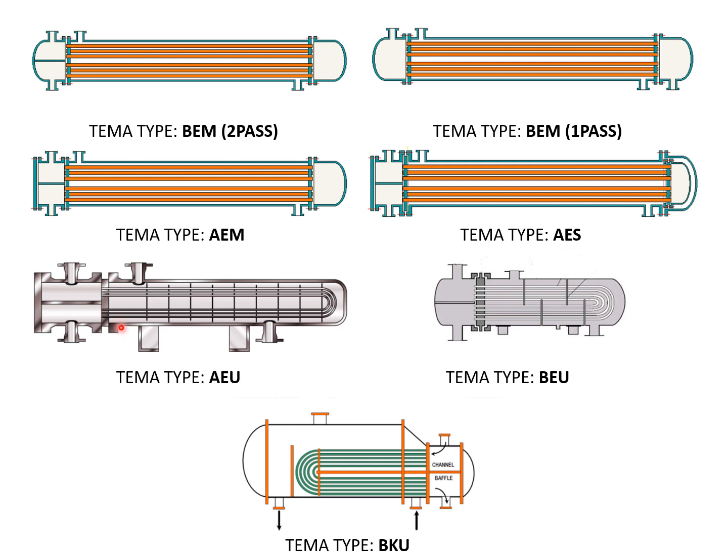So AEU. AEU means you have A, same as this exchanger. You have a removable type of bonnet over here. Then you have the same E, one pass shell, but here you have U-tube. U-tube means the end of the exchanger will not have a bonnet over here, but the liquid which is going through the tubes will have a bend in the tube itself. U-tubes are ready-made tubes available in the market, and the liquid will come over here and come out. This is called AEU, and this is BEU because this is not removable type.